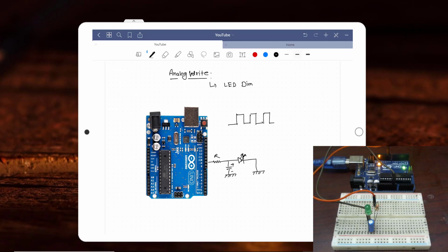if we apply a capacitor, then with the capacitor we can get a wave like this. If it is 0, then with the capacitor it doesn't come to 0 directly, but the capacitor starts discharging, and then once it goes to 1, the capacitor again charges, and then discharges, charges and discharges. So ultimately, if we add a capacitor here, the LED doesn't go off when your voltage is off at pin number 9.